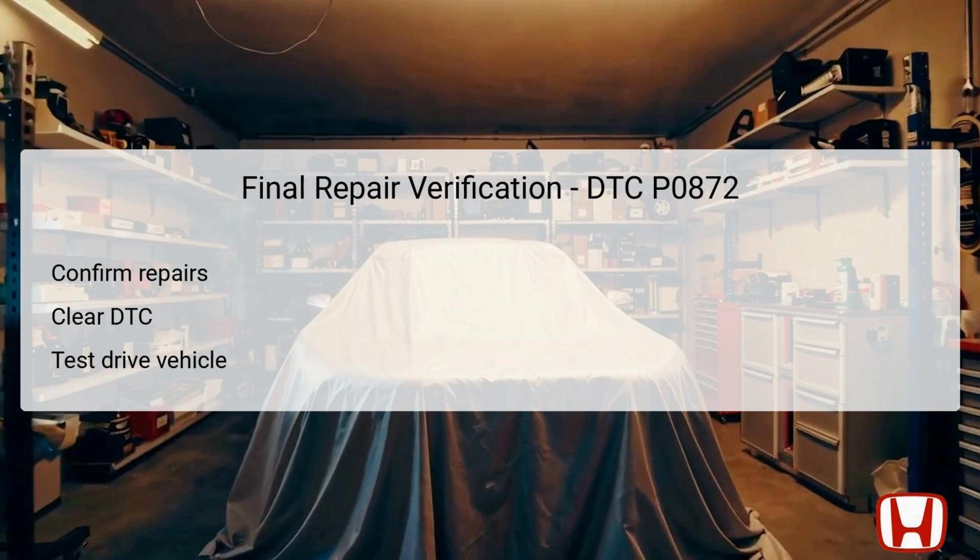Once all necessary repairs have been completed for DTC P0872, it is vital to conduct a thorough final verification process to ensure that the issue has been resolved. Begin this step by confirming that all repairs and replacements have been meticulously executed, paying careful attention to connections, components, and wiring integrity. After confirming repairs, proceed to clear any DTCs using the HDS, resetting the vehicle's diagnostic system.